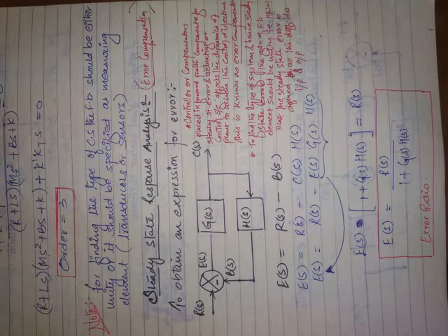Now listen here. A controller or a compensator placed in the forward path compensates for steady state errors and sends an actuating or a control signal to the plant, affecting its dynamics to ensure that the output remains at the set point or input value.